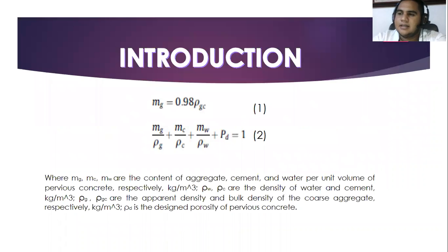In cities, there is a large presence of impermeable surface, and this generates problems. But the concept of pervious concrete would mean thinking about the environment and reducing problems, in addition to the absorption of acoustic noise. Some authors point out that this type of concrete is based on the adequate selection of thickness, the water cement ratio that varies between 0.27 and 0.43, and the aggregate cement ratios that are 4 to 6 by mass.